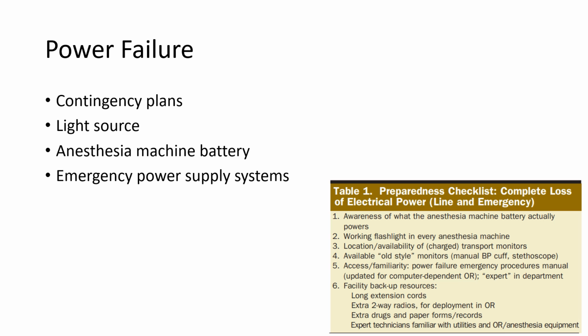Finally, it's important to know about your hospital's emergency power supply, i.e. generators, and importantly, know that red hospital plugs are the ones that are functional in the event of generator use. So important equipment should always be plugged into red outlets, so in the event of a power failure, those will continue to function once the generator kicks on.